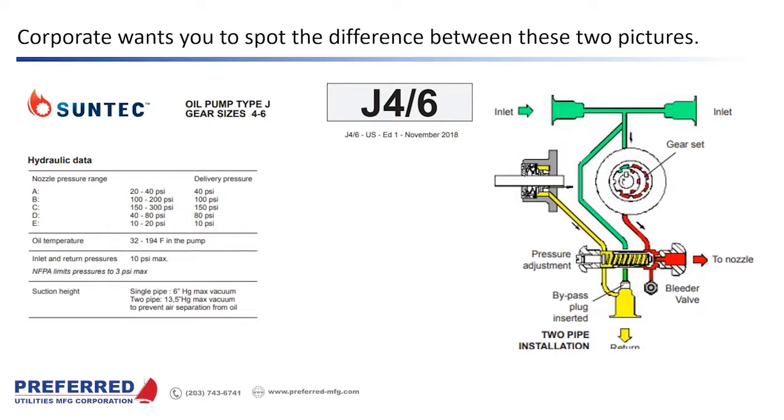Occasionally, in fact, I just saw one yesterday, I saw a boiler design that had a day tank next to each boiler, and transfer pumps pumping from a main tank to all those day tanks. And there's really no reason for that. It adds a lot of money to the project, and nobody wants to have oil stored inside their building if they can help it. And why would you take the risk of potentially overfilling a day tank when you don't have to have that day tank?